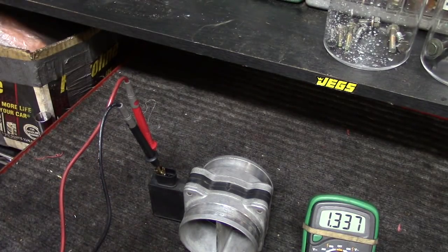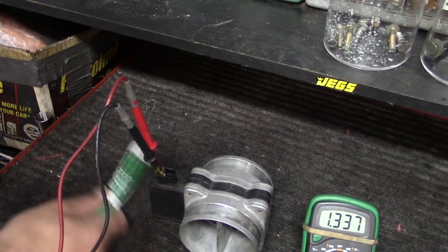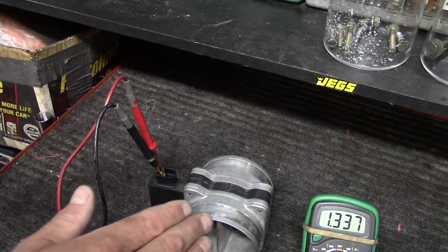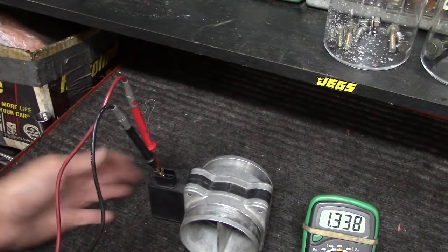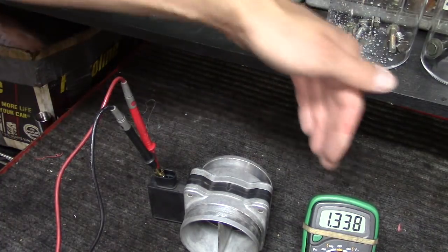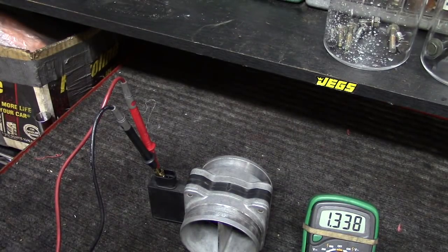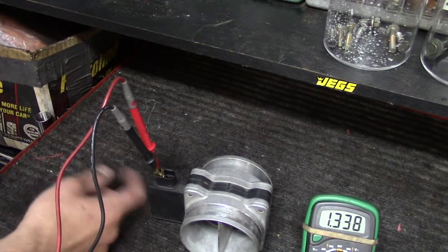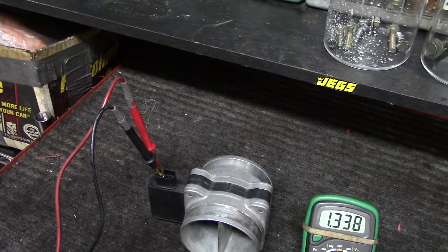Now another thing that you'll want to do here, and you can also do this on the car if you wish, you don't have to remove the sensor, but you want to be very gentle with this, is tapping that MAF sensor, just in case the wire is broken but it's making intermittent contact, and you would see a dropout here. We can see that we don't have any dropout, and of course this is probably better done with a scope because of the speed, as well as doing this on the car, maybe with the car running and using a scan tool or something to look for dropouts. But that's something you want to consider with those MAF wires, and we don't have any indication of problems there.